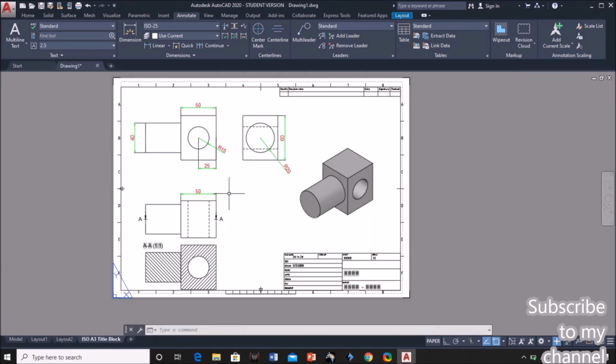And if you want to give the text for these views, go for the text, that is multi-text. Enter. So this is the command for the multi-text. Just specify the first corner and other corner.